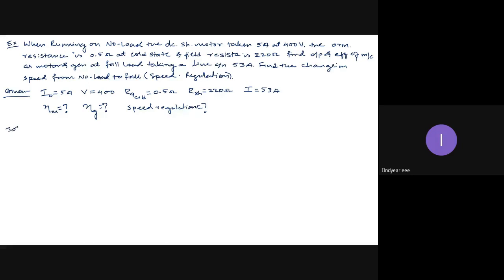Solution. In the previous example, it was not mentioned whether the given resistance 0.9 ohms was a hot resistance or cold resistance. In such cases, by default we have to assume that as hot resistance only. But here it is mentioned that the given value 0.5 ohms of Ra is cold resistance. So now I have to transfer it to hot resistance.